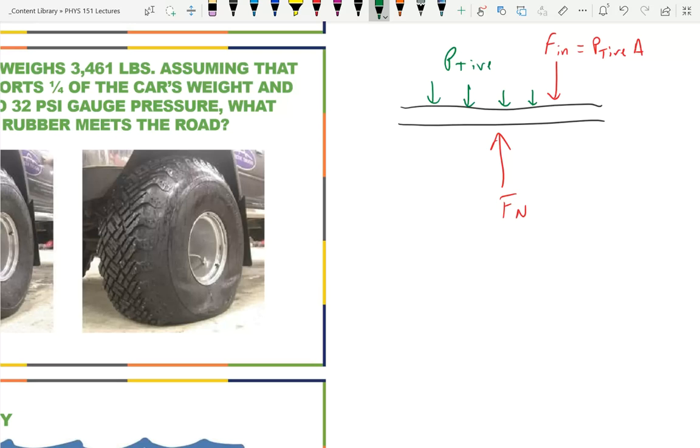And what direction is the force that the atmospheric pressure is going to put on this piece of rubber? Normal to the surface going in. Always going in. There's no such thing as a negative pressure. A negative pressure would mean a force pulling out. You can only do that if you glue your hand on, right? If you were to glue the fluid to your material, well, you can't do that.